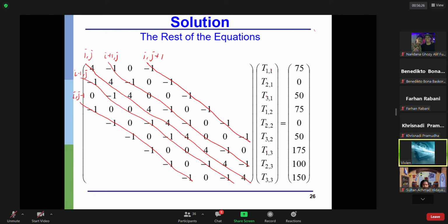So when we look at this, we can extend further. For example, if we have third order, we have 3D, for example, 3D heat conduction. So we can do the same as well. When we have 3D heat conduction, we expect that there will be a dependency to K as well. If we extend to 3-dimensional heat conduction, for example, on a cube, we will have K here. That will be the dependency with K plus 1, and that will be the coefficient to the dependency to the K minus 1 point. So this will be the example.